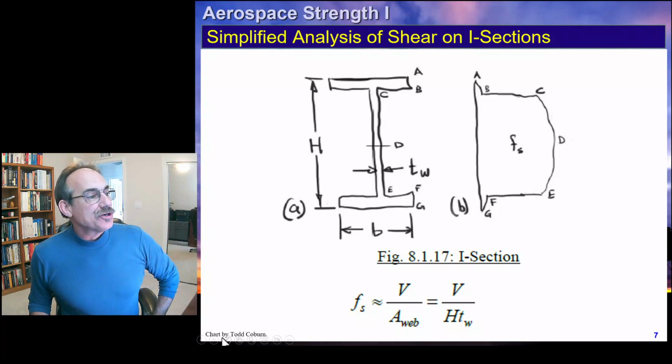In order to get the shear stress distribution, we have a few calculations. We need to recognize that at the top, the shear stress has to be 0. We would then calculate the shear stress right here on the wide section to get this value. We would then change that same value by evaluating it on the narrow section, that T web, to get this value. Then we would take a Q, add the Q.